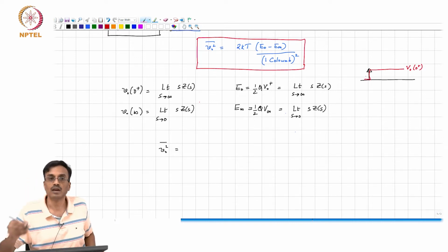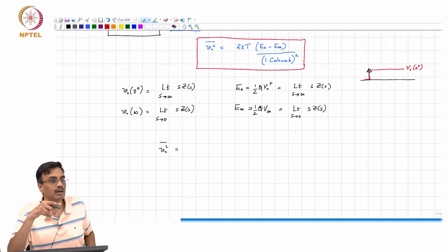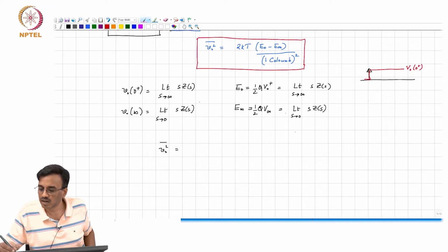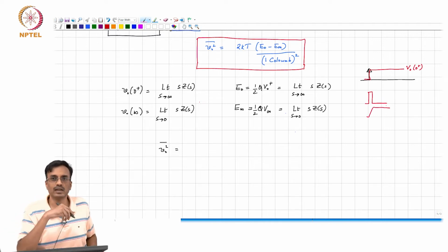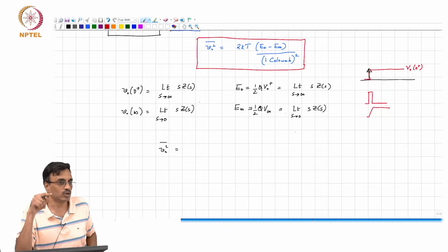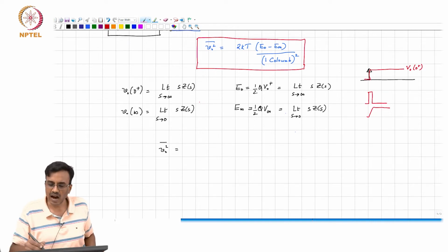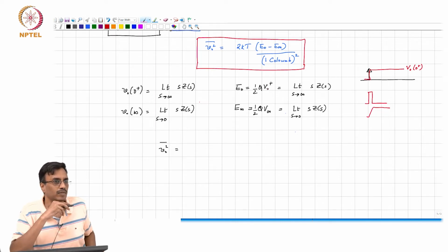It is simply the integral of the voltage waveform times the current waveform that has gone into the network, and you can see that, I mean there is of course a discontinuity, but if you interpret the impulse as being, for instance, a thin pulse and the voltage waveform doing this, it is very clear that the energy that is there inside the network is half q times V of 0 plus.